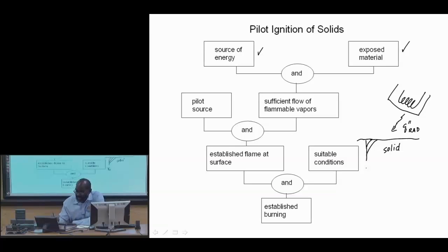As we get this thermal propagation, thermal wave within the solid matrix, the solid molecules or polymer strands begin to decompose. So, for example, if we had some polymeric system, we get breaking of the backbone bonds, we get breaking of some of these branches off of it. And so this decomposition process is often called pyrolysis.